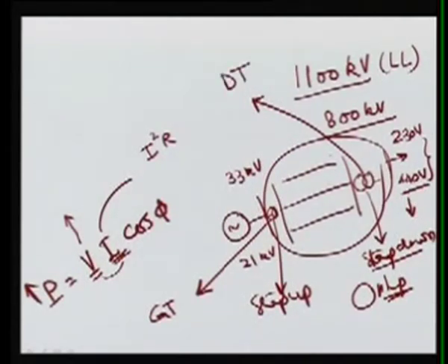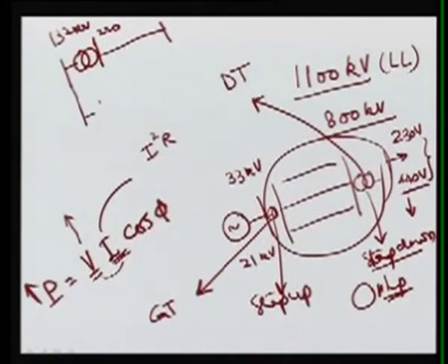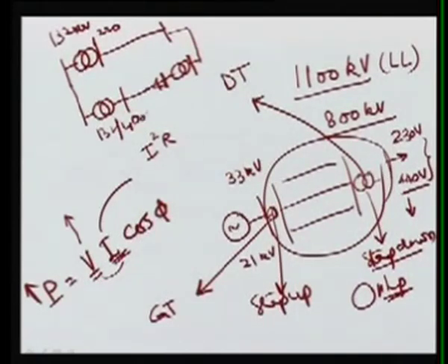The transformers in between the transmission lines, for example, if you have a 132 kV bus, then you want to lift this voltage to 220 kV, and then we have this line. There is a possibility we have another transmission line, and then we lift it to a 400 kV line, then we have another transformer, and then we connect with the system here. So this is your maybe 132 by 400 kV, this is your 132 by 220, and again here we have 400 by 220 kV transformers.